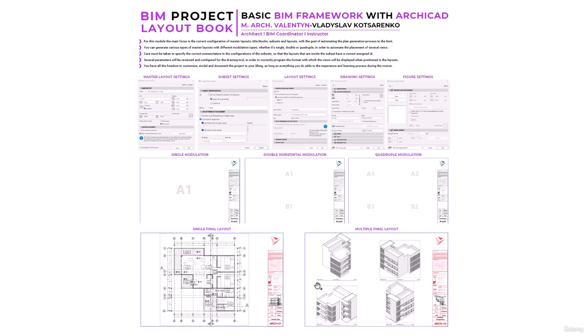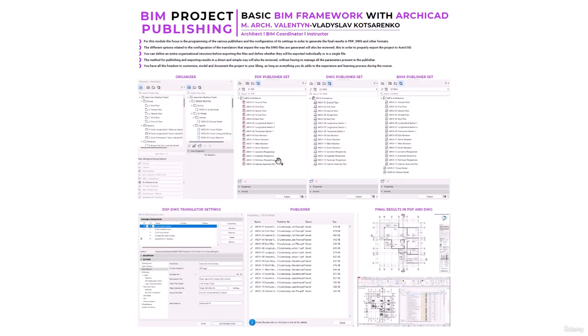And once we are done reviewing all the concepts about layouts, this is where we begin with the last steps, one of which is the publishing process, where I'm going to delve into detail about the organizer, the publisher sets, how you can export in different formats in one fell swoop, how you can export something specific as just one view in the basic manner, but how you can also use the publisher to export everything in just one go, in formats such as PDF.